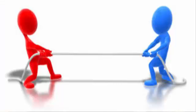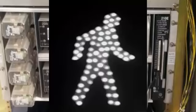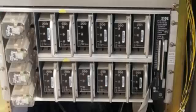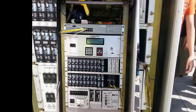Number 1, to check for simultaneous activation of conflicting phases. Number 2, to check for absence of a red indication on a phase that does not have a green, a yellow, or a walk. Number 3, to check for insufficient operating voltage that is usually due to power interruption. Upon the detection of a malfunction, it immediately places the intersection into latched flashing operation, which basically means all lights flash red.